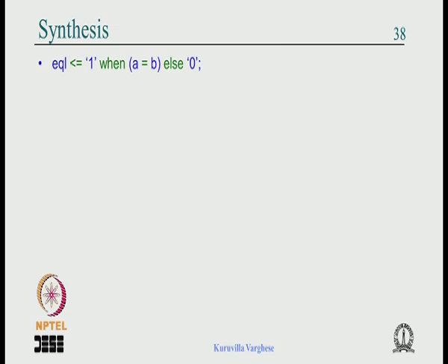Think of a mechanism by which anything you write, at least for a combinational circuit, can be synthesized. Do not worry about sequential circuits, or what the VHDL code for a flip flop is, that we will handle later. But for a combinational circuit, you write some statement, what is a sure way of synthesizing it?